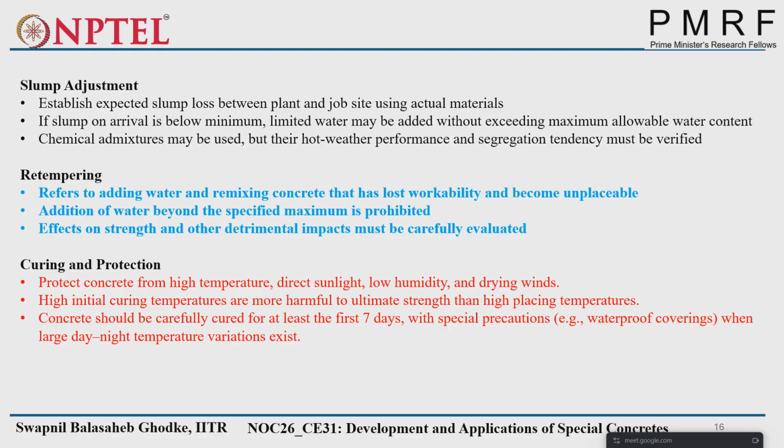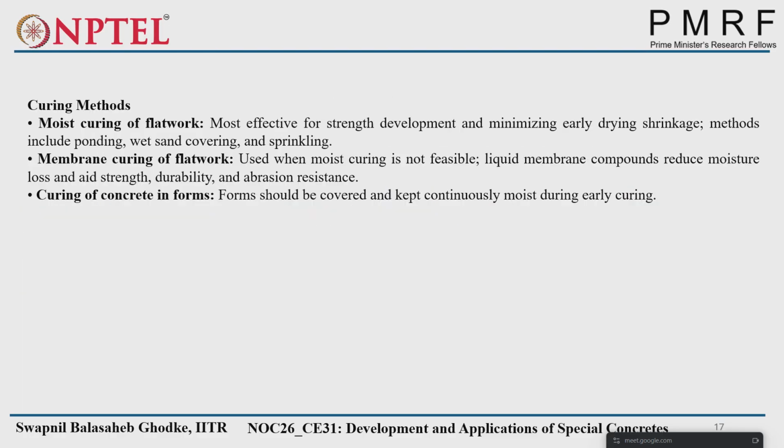In cold weather as well as hot weather conditions, we have to take care of the curing conditions in the initial hydration days, like the first 7 days. Here it says that in cold weather it is almost 36 hours. After that, whatever temperature changes occur will have negligible impact on the strength or durability of the concrete. So we have to be careful about the initial phases only.